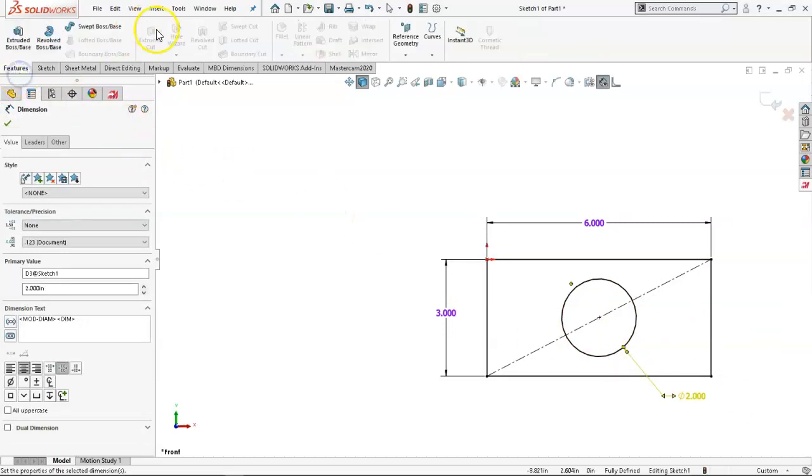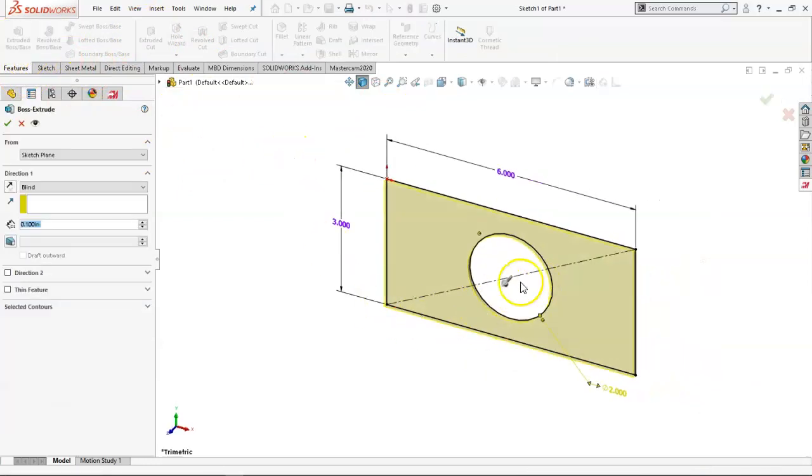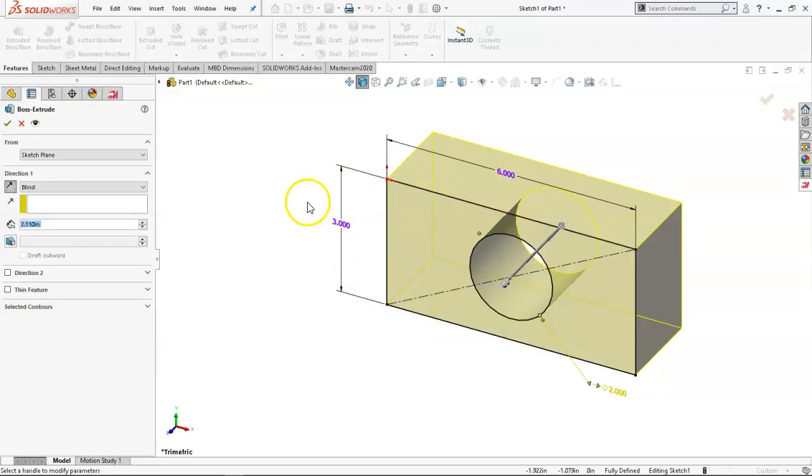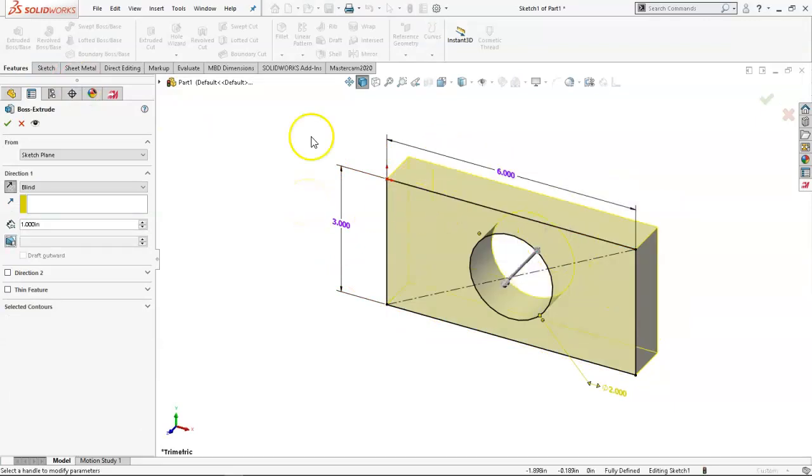And then I'm going to extrude that out. Depending on which way I extrude it, usually I want that front plane, and I try to work in the Z negative. It makes sense to me. So if we tell it that it's a 1-inch block, then by default, most of the CAM packages are going to pick that origin. What we don't know is if the CAM system is going to pick up the same Z, or if it's going to rotate over, which, yeah, is pretty minor at that point. But a lot of the CAM packages are going to see that origin. It's going to be X, Y, Z.